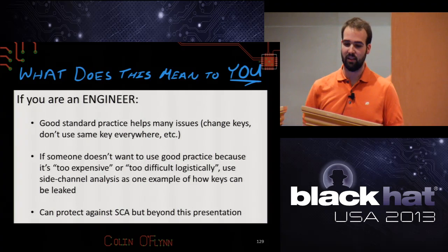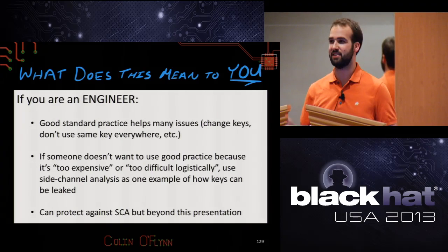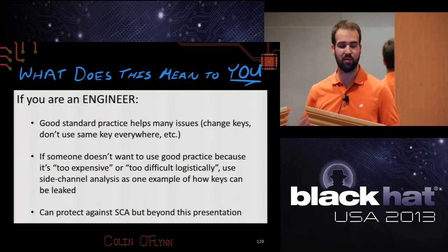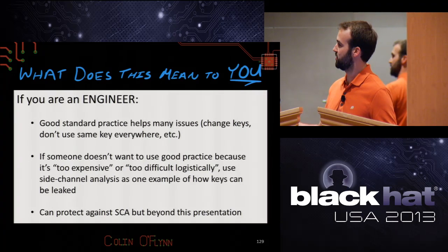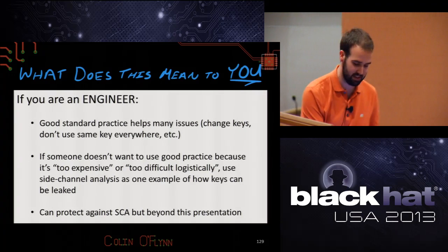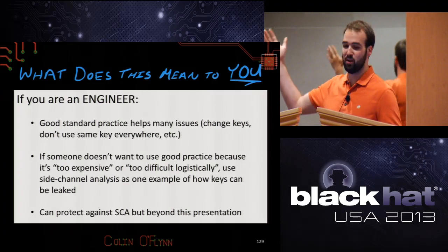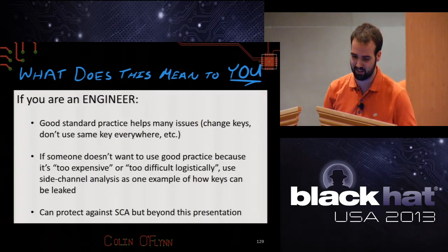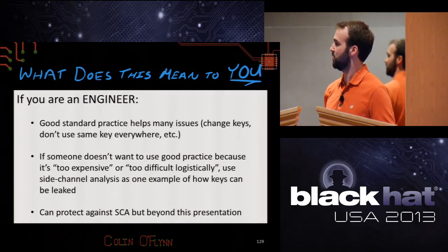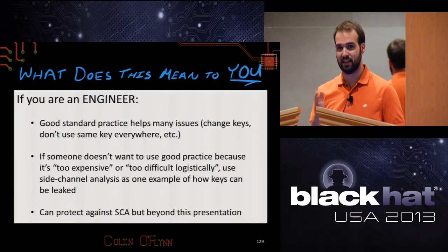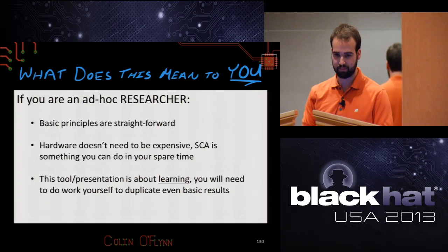The problem is that a lot of people don't want to use good practice because they say, well, that's a hassle. I'm not going to have different devices with different keys in their bootloader and then different firmware files. So maybe this is a good way to point to say, well, here's a reason we should do it because here's an easy way people could be breaking our systems. And so you can use this to point out why we should use good standard practice. You can also protect against side channel analysis. So there's hardware and software things you can do that make this analysis much more difficult. And it's sort of beyond this presentation.